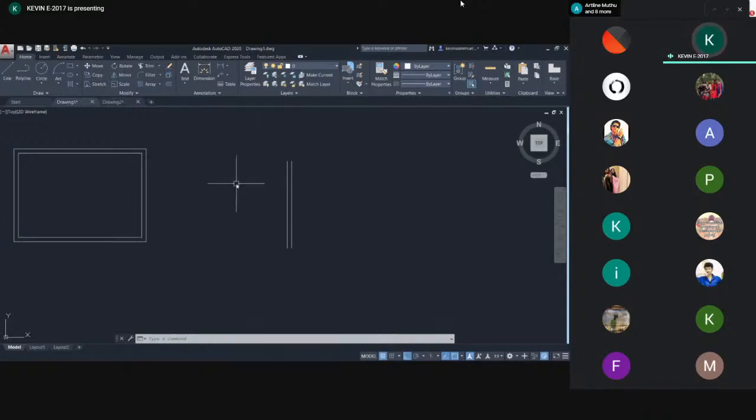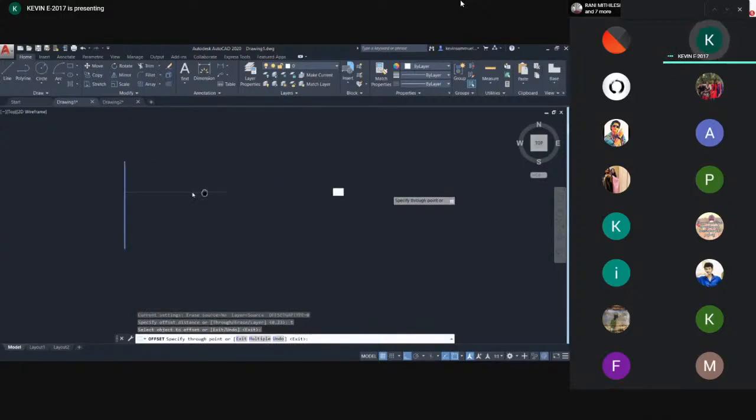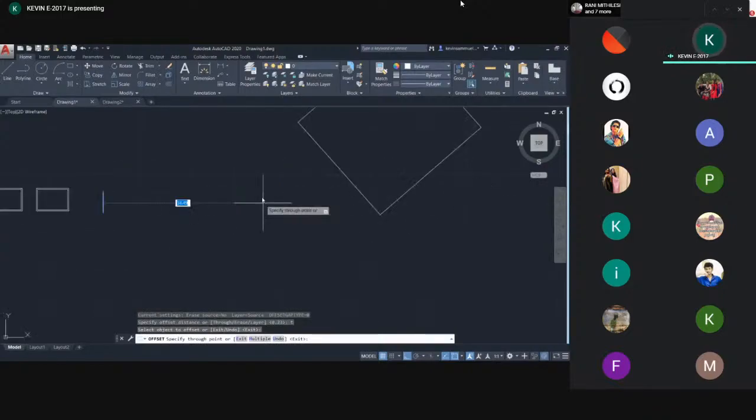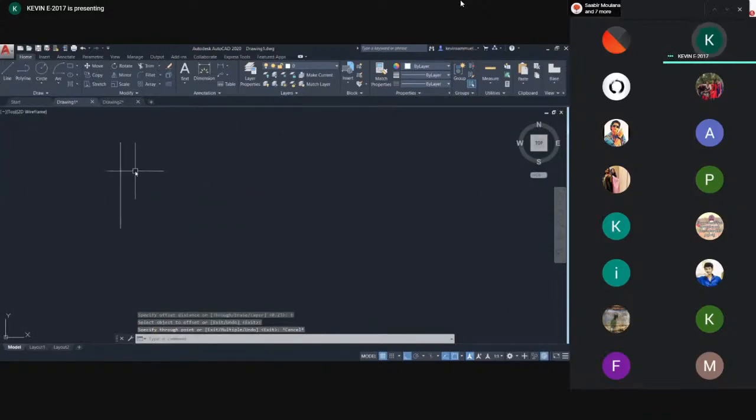And if you want to move freely by an offset distance, you can press O, and the distance is always set to 0.23. If you want to move through any n number of distance, you have to press T. So you can see here through arrow. You can press this, and you can move it however much you want, to any kind of distance. So that's what offset does.